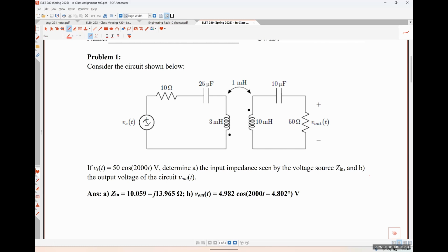So anytime that we see a circuit that contains resistors, capacitors measured in some type of farad, and inductors measured in some type of henry, we need to first convert this into the frequency domain so that we can do all of the normal circuit analysis that we've been doing. You should be aware of these relationships, and we have used them in this class before, but I'm just going to remind you that the impedance of a resistor is just the resistor value itself.